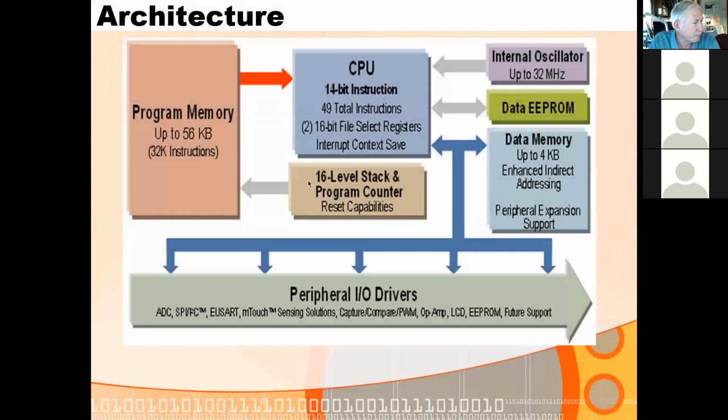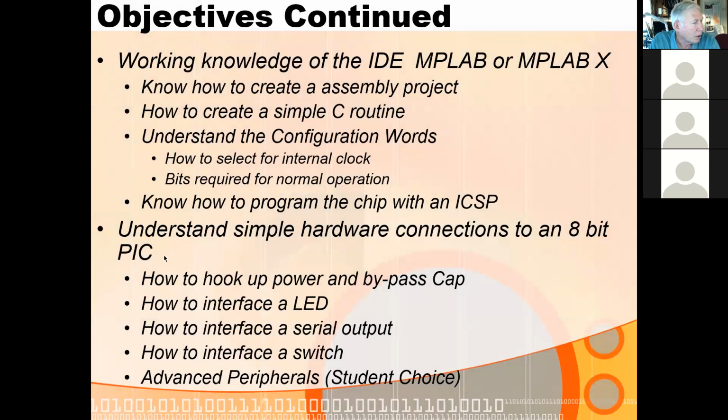Okay, let's see. Did we get through this? You should also understand how we put the Viva board together, why it is what it is, and what everything on it does. You should know why we have the bypass capacitors, why the RGB LED and the other two LEDs all have current limiting resistors for each of their colors, how we put in the UART to USB interface and how that works, and how you can interface a push button using the jumper in the RB7 push button position and using the little button for that.